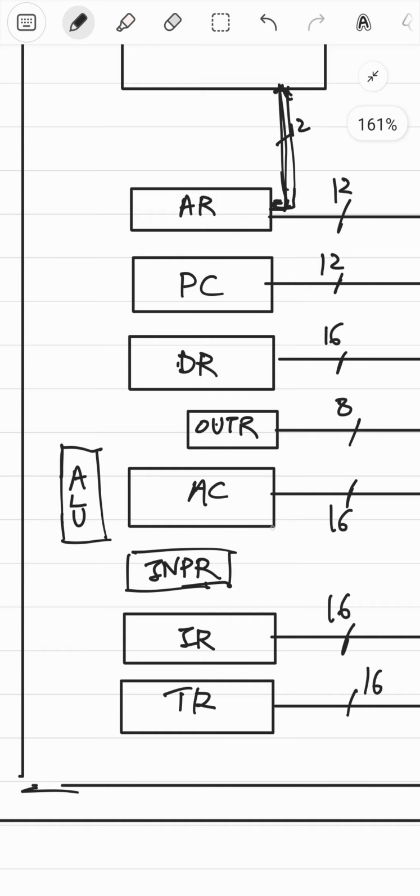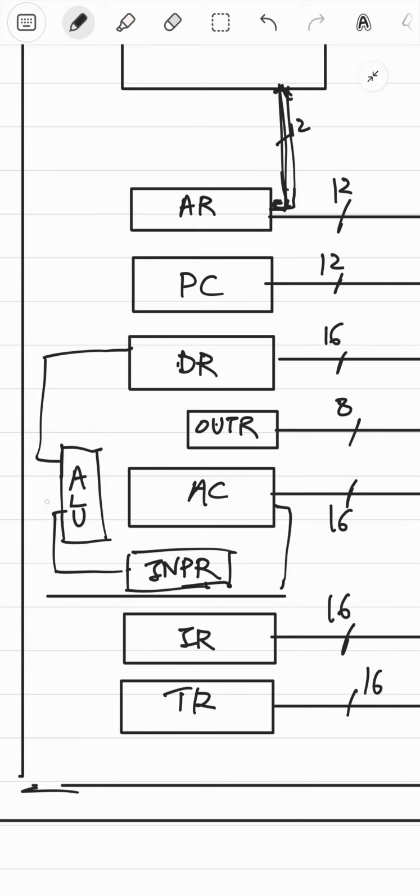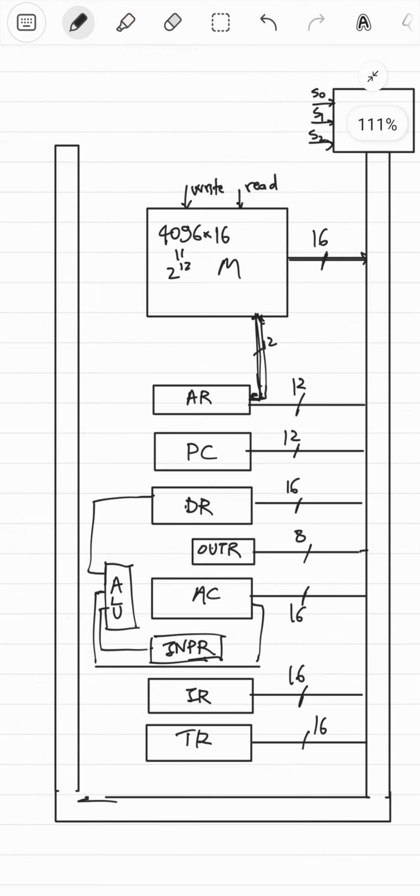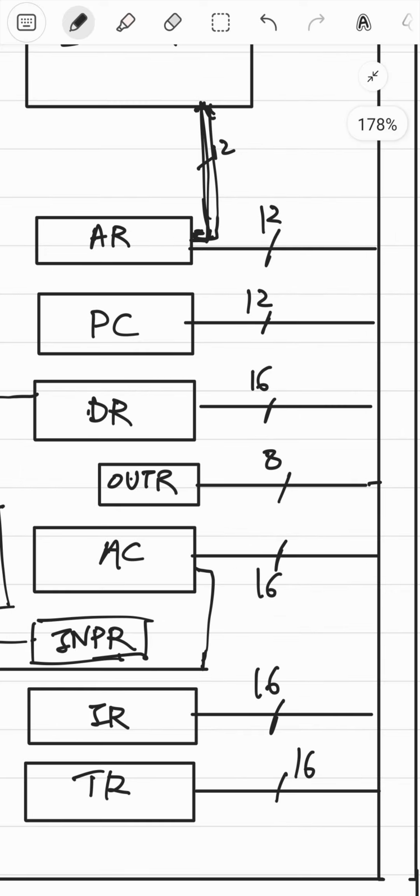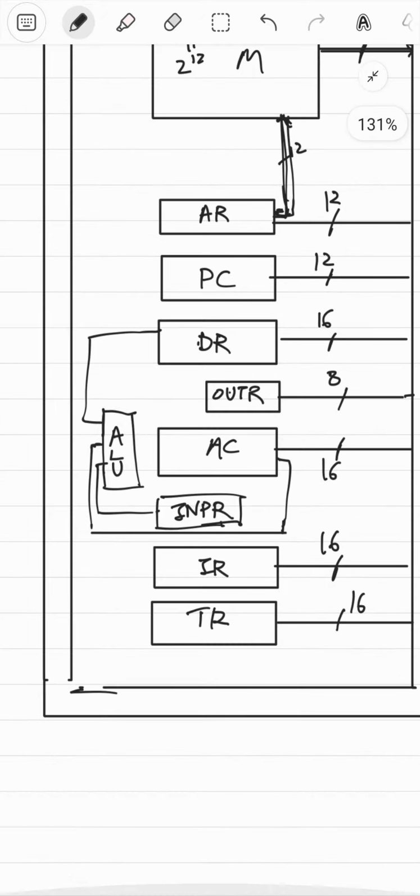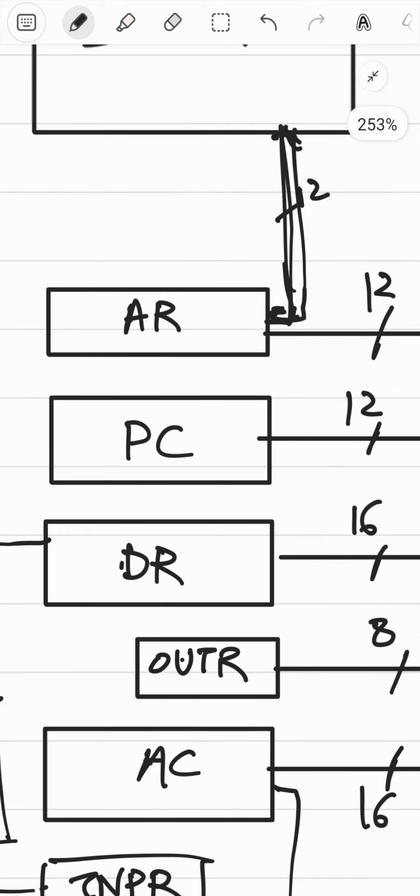First of all, you have this thing connected to it, you also have the data register connected to it, and also the accumulator itself is connected to it. What this means is that you can do, say, the complementation of the bits in the accumulator in just one clock cycle. Oh, I should also draw the clock signals.